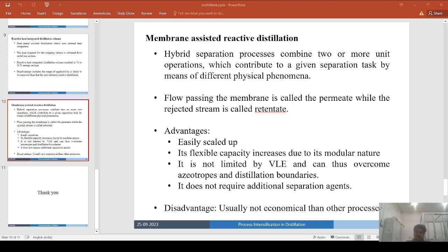So the microwave irradiation can lead to an accelerated separation of one or multiple components via vaporization in the reaction system, to overcome the equilibrium limitation and impel the reaction in the desired direction. For example, an industrially relevant demethylation reaction by microwave can prove the effect of breaking the equilibrium constant through the elimination of gaseous byproducts such as methyl bromide by microwave heating.